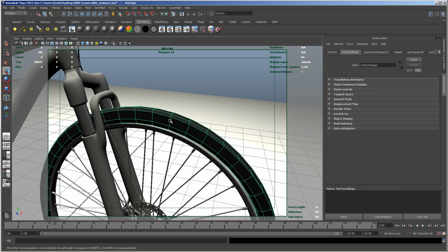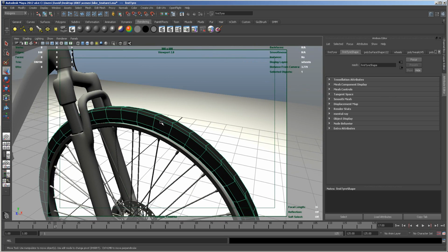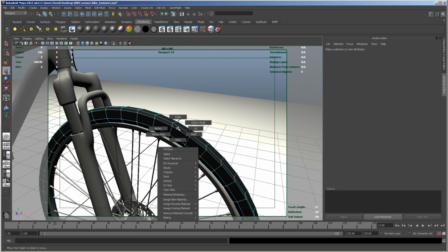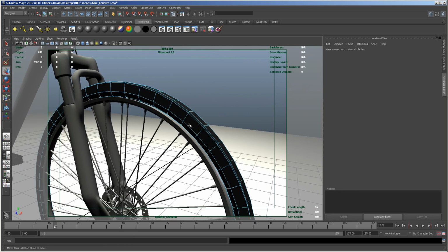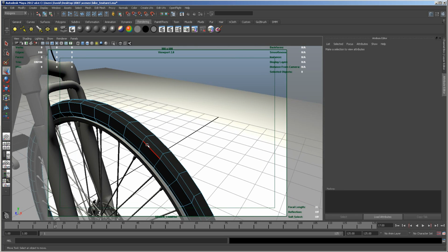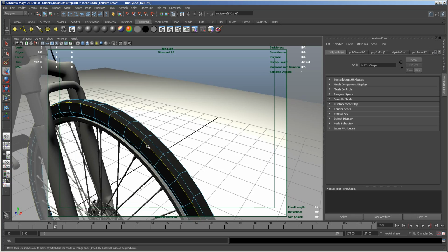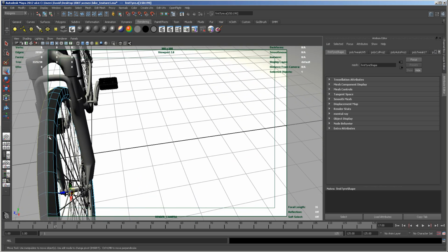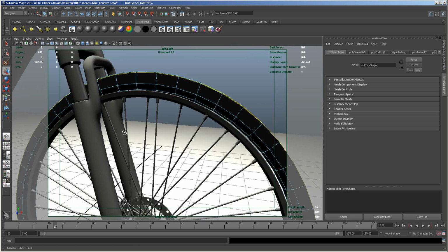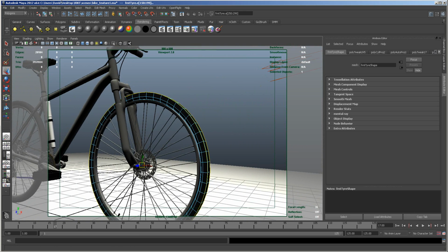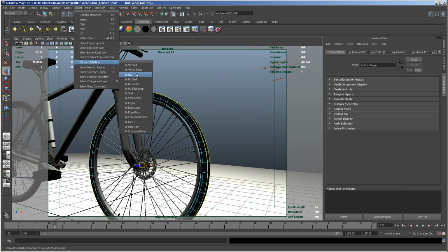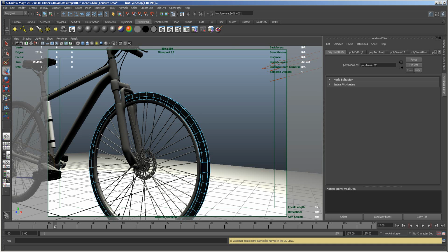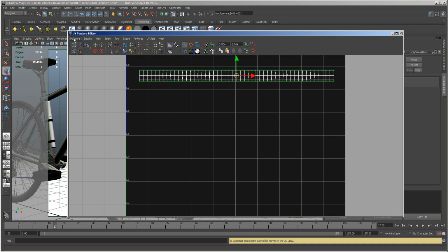Okay, yeah, what I need to do, sorry, is just to select the edge, and make sure I've got the right edge, which is here. Yeah. Then I'm going to come on to the other side, hold the shift key and select that. That would have formed edge loops around there. So I now want to go to select, convert selection to UVs. Inside of here you'll see that they're UVs. We go to polygon and then split UVs. Okay, that will split them away from the sides.